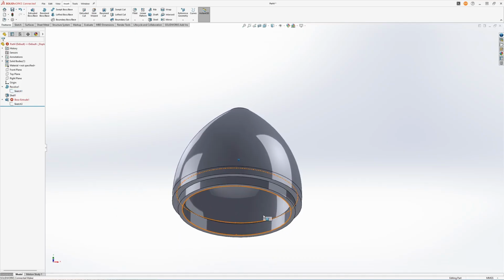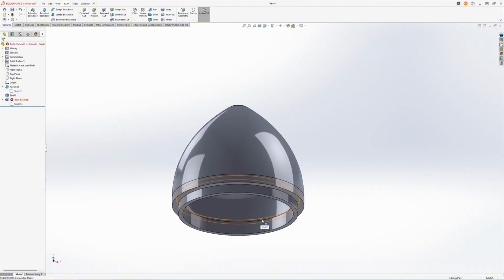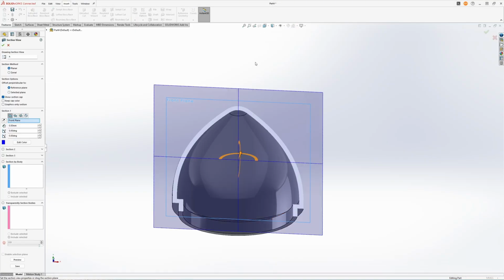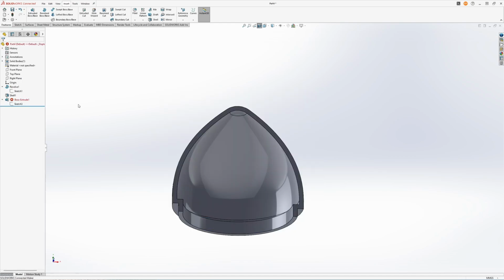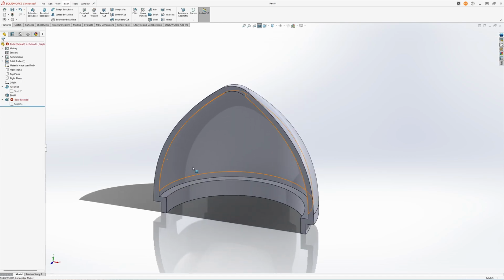The surface here will have a specific ID, and that ID is now new. So now this one can't find out where it should actually draw this feature, because the face is different. So sometimes you have to go back and repair things that you've done when there's bigger changes, but in this case it's fairly straightforward. Let's have a look.